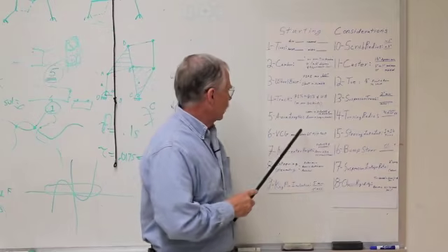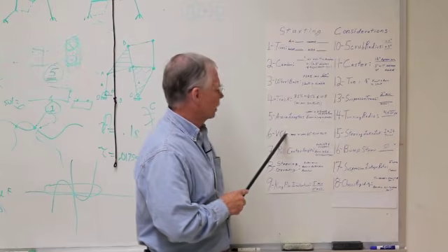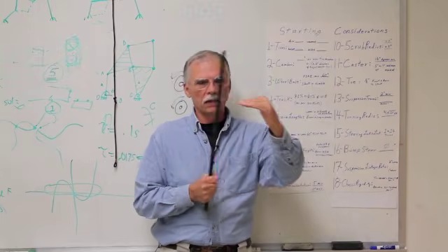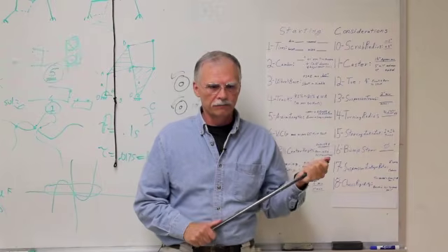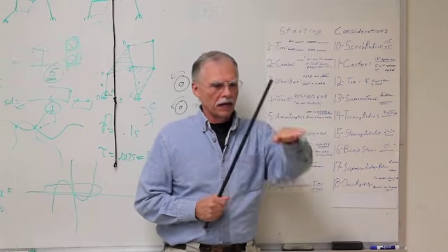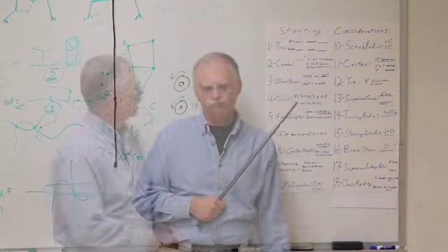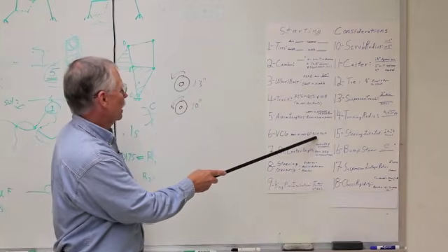In order to do that, the vertical center of gravity of the car has to be below a certain level and has to be relatively centered in the car. If it's above that, the car, when it goes up on the tilt table, is going to roll off the tilt table. All right, 60-degree tilt test.